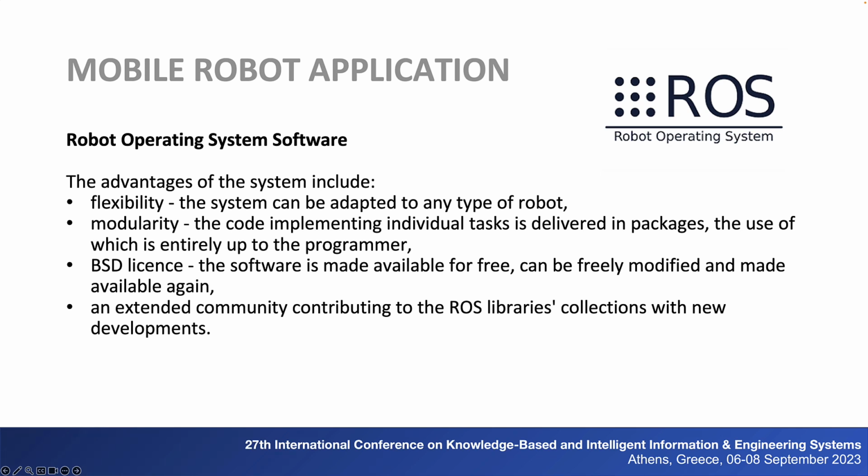Nodes are responsible for the operation of a robot whose software was executed in ROS. They are small programs that run independently of each other and are usually responsible for performing one specific task, for example, setting the speed of motors, reading data from distance sensors, etc. The individual nodes communicate with each other using messages composed of simple integer, float and Boolean data structures.